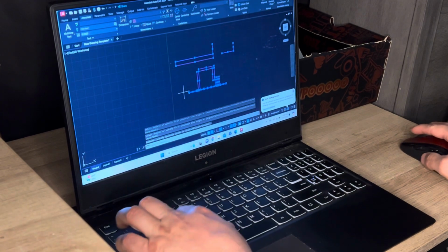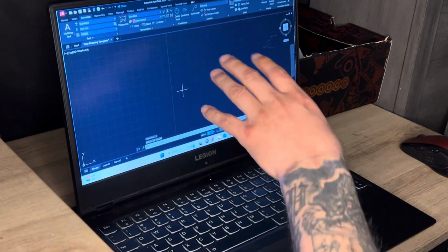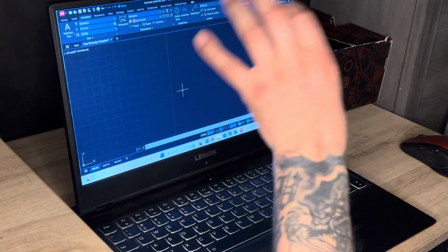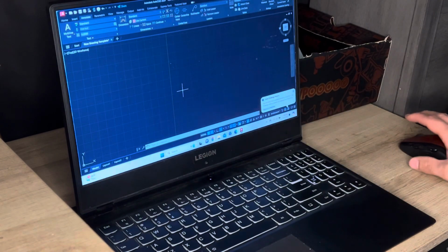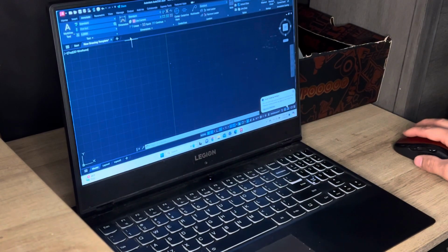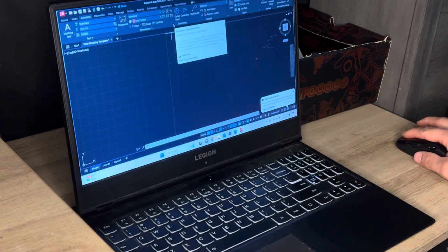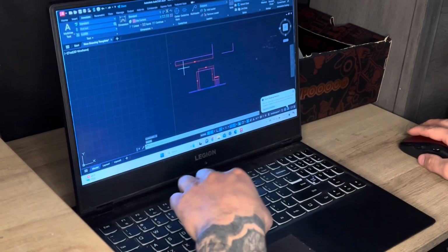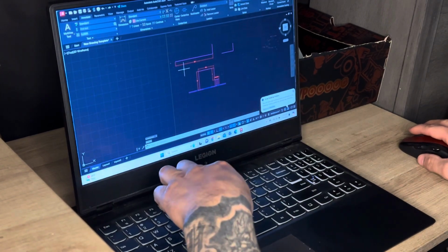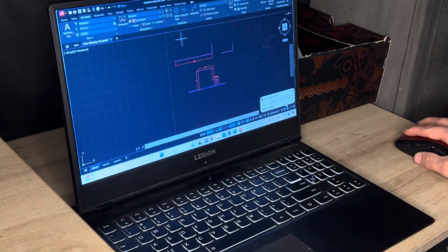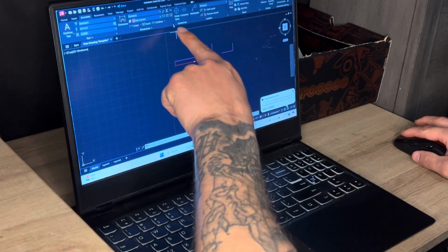So you want to build your first drawing that you're doing, just name it new template, and save it as new template, and use that drawing. Build your tools first. So if I click up here, there's going to be a manager, right? Dimensions. Well, first I want to have objects to be able to check it off of, so I just hit U and then space, and that undid my last move, which was erasing all that. But I go up here, there's a little arrow right here.